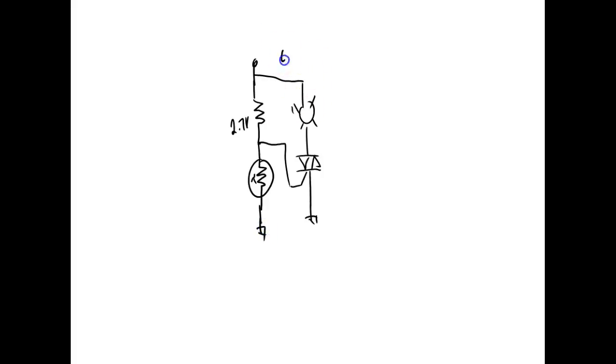Putting 6.3 volts AC right there. That's coming off my transformer. I'm taking it off my center tap. And this is all there is to that little circuit. We okay?